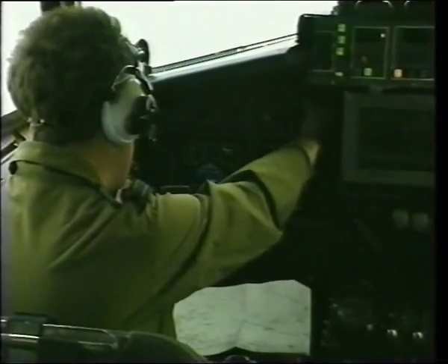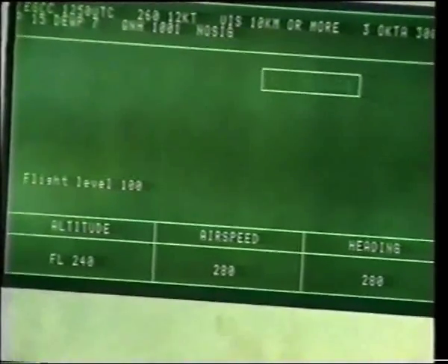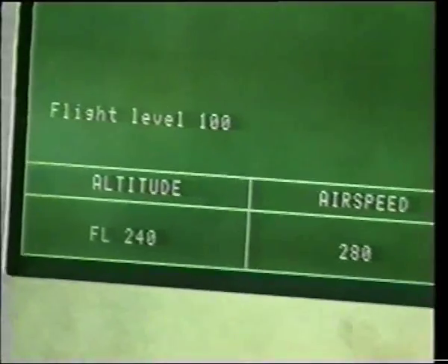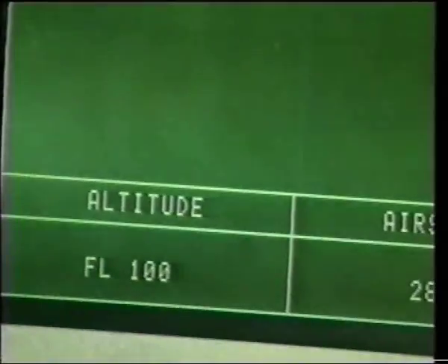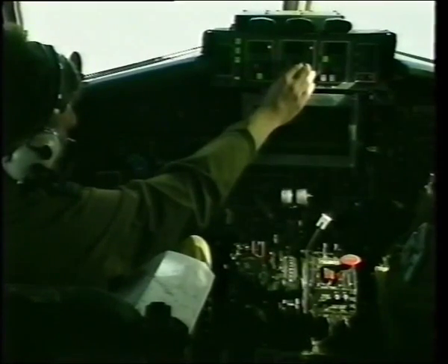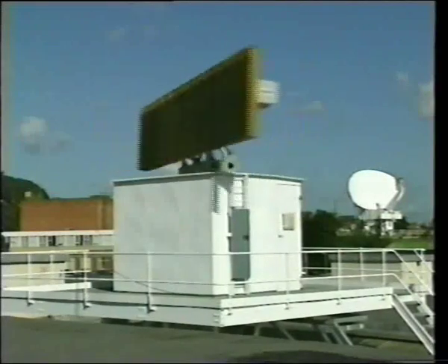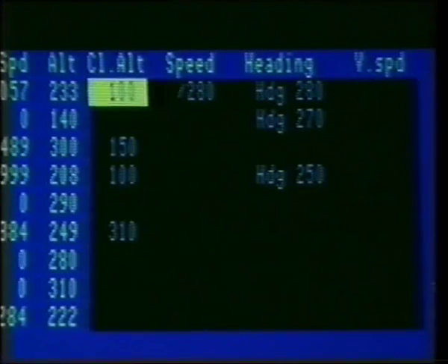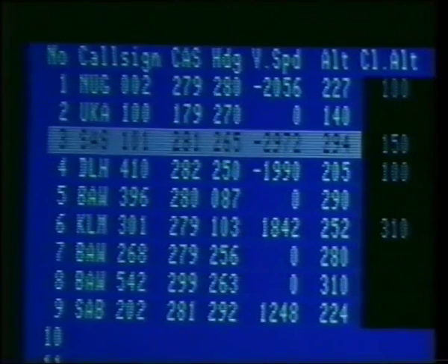The pilot is alerted on his map display at the same time as the datalink message alert is activated on the LCD. Pressing the acknowledgement button, the new instruction transfers to the altitude box. The autopilot can now be reset. Now being downlinked via the datalink processor and on the ground processed via the DALAP and ACE processors, the acknowledgement is passed to the controller and the yellow overlay is removed.